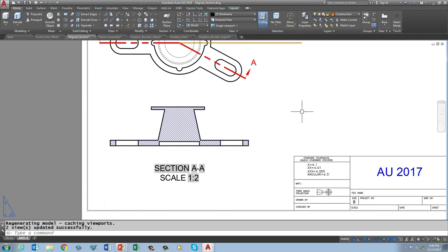And they're associative. How do you erase one of the objects in the array? Control, pick, delete. Same thing. Remember the two fancy keys in AutoCAD: Control and Shift. If Shift doesn't work, try Control. If Control doesn't work, use Shift. That's called sub-object editing of a model or a 2D model.